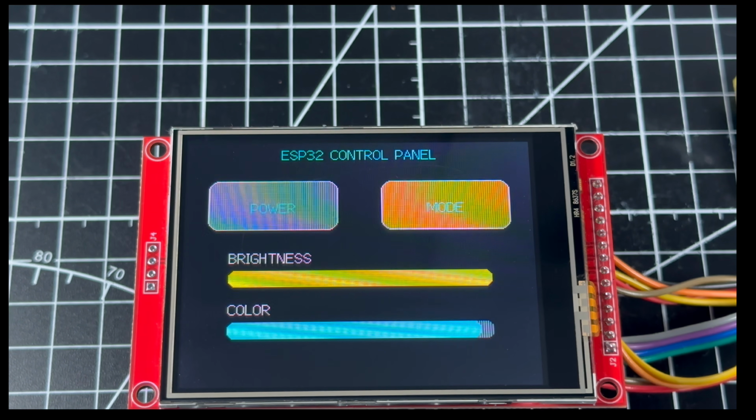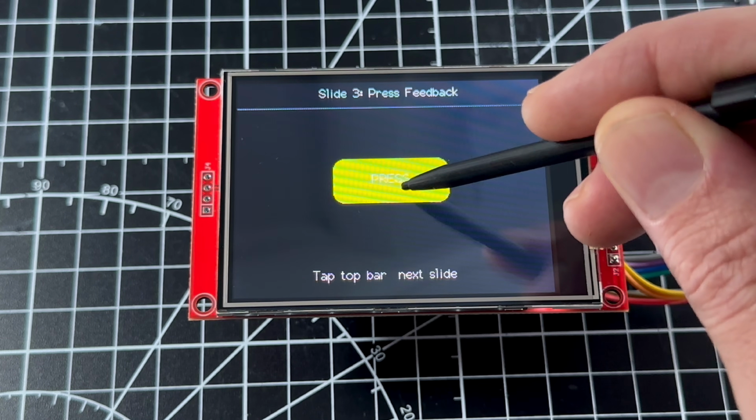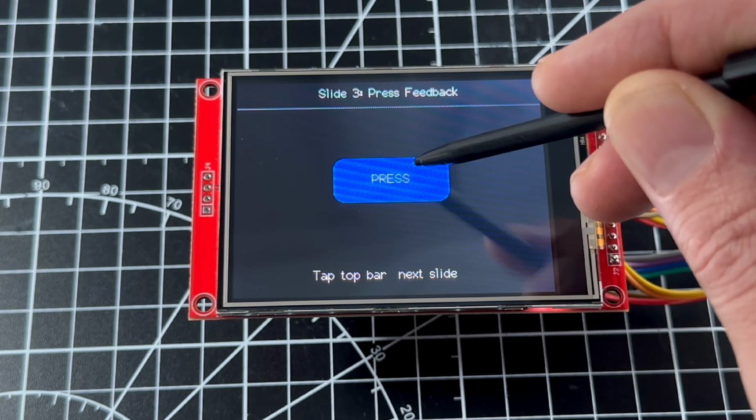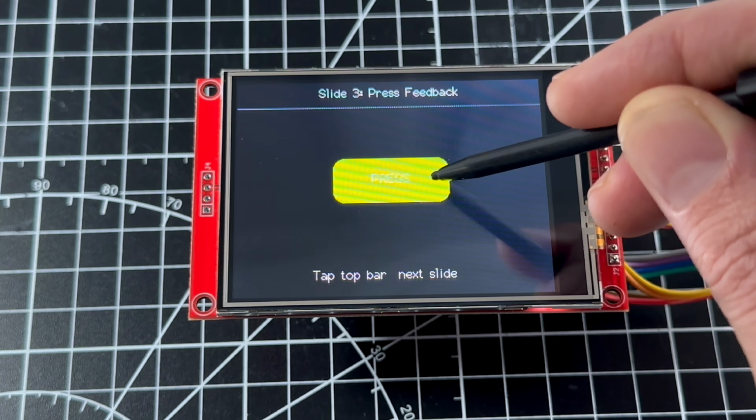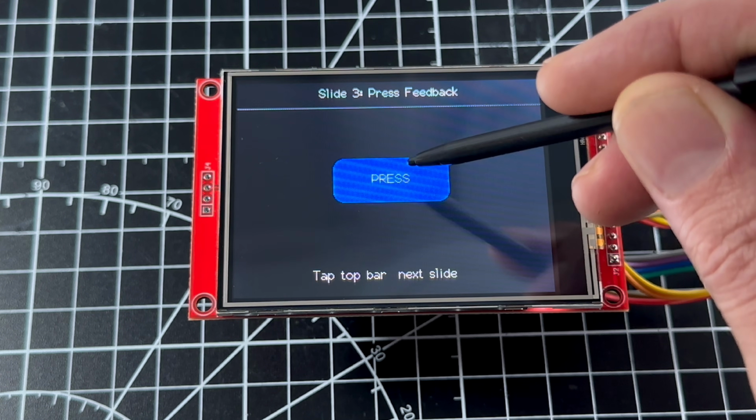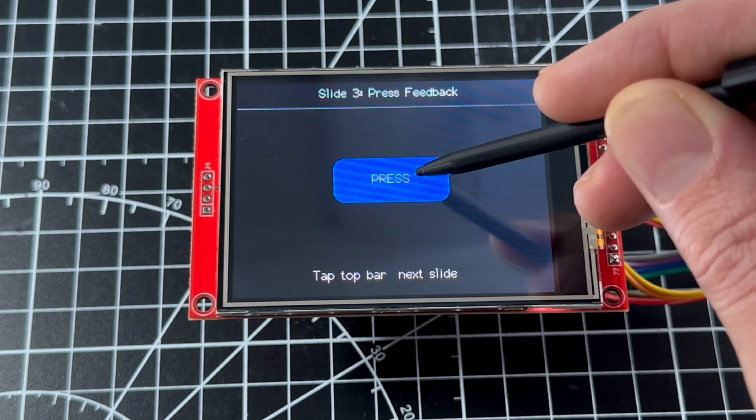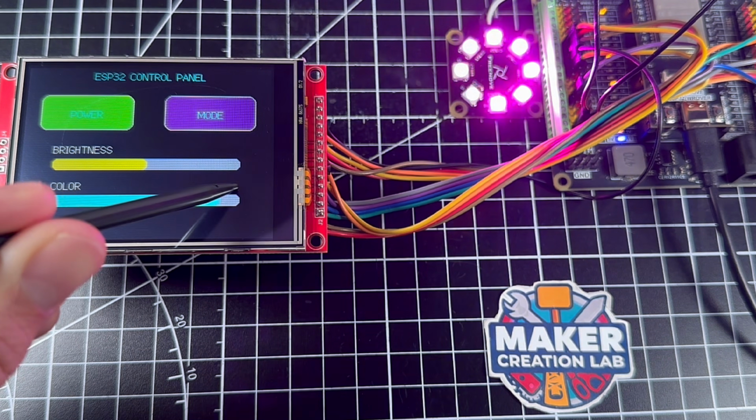If you press the button once, the ESP32 might think you tapped it 10 times in a millisecond. The fix? We implement a timer. We tell the code, once a touch is detected, ignore all other touch signals for the next 200 milliseconds. This is called debouncing.